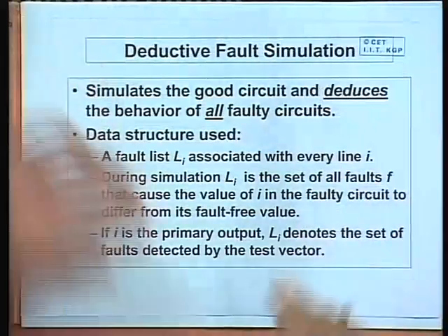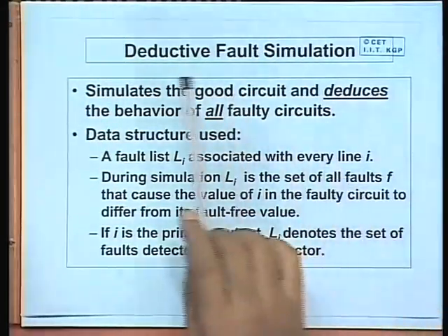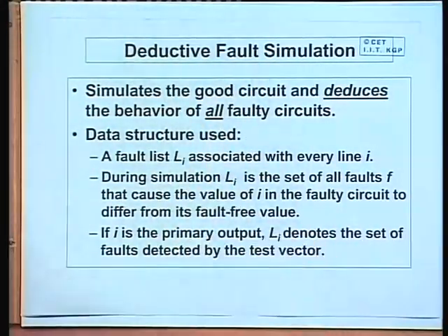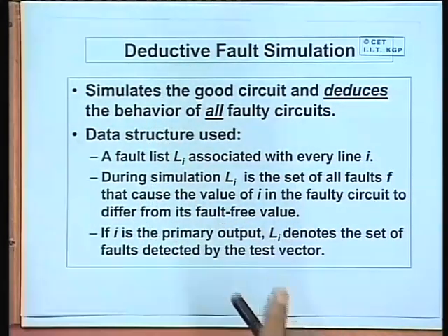Let us look at some other fault simulation techniques like deductive fault simulation. Now, deductive fault simulation is an interesting method. This is an event driven fault simulation in the sense that you only simulate a gate if some event occurs in one of the inputs.